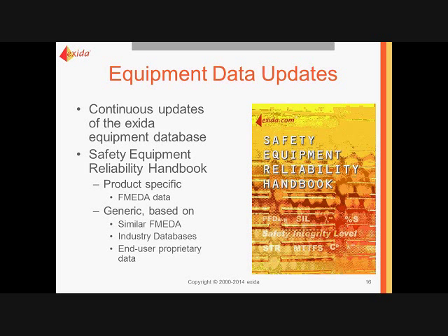But if you're looking at it and just doing certification based on cycle testing, then it's not a realistic test for that particular application. So some failure rate data that we've seen that has been produced as a result of cycle test data is significantly more optimistic, and in our opinion is misleading and dangerous.